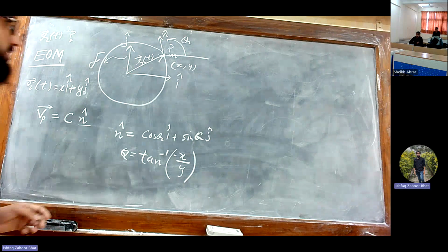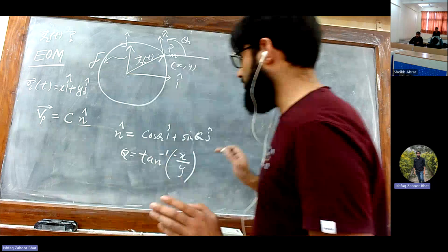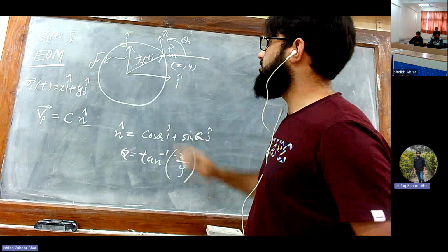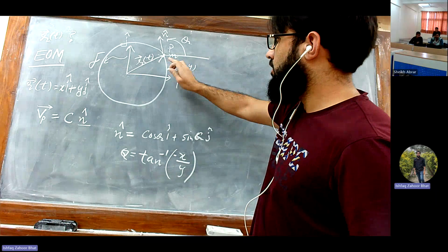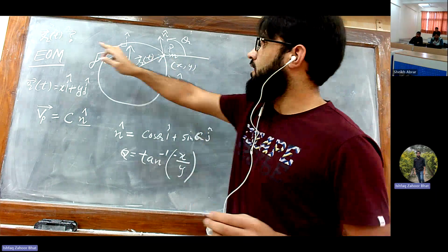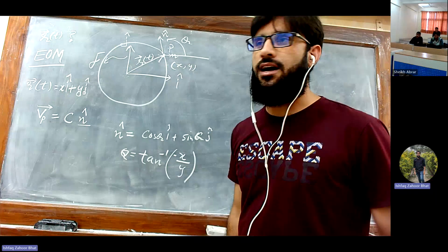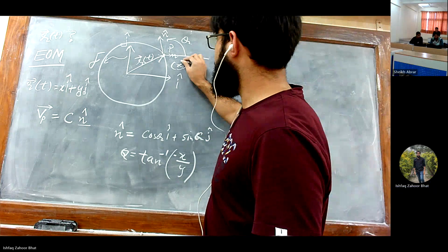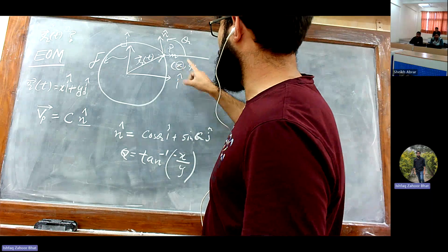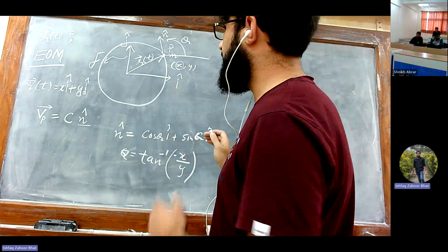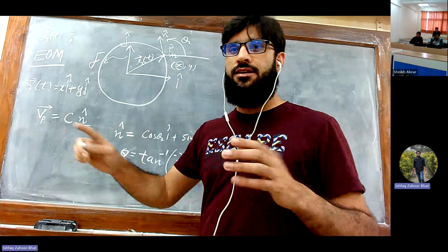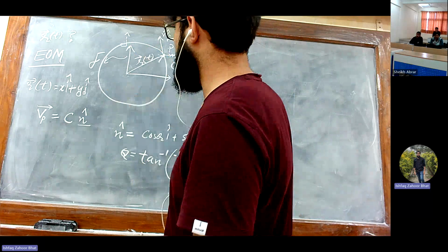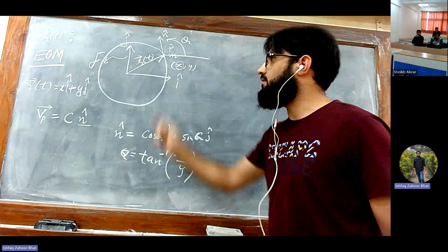So what next? What we want to do today is that we want to simulate this particle. That is, we want to plot this r of t with the time in Matlab. So what we are basically going to do, we will find this x and y as a function of time, so that when we vary the time, the x and y will vary in such a way that the x y point will lie on this circle.